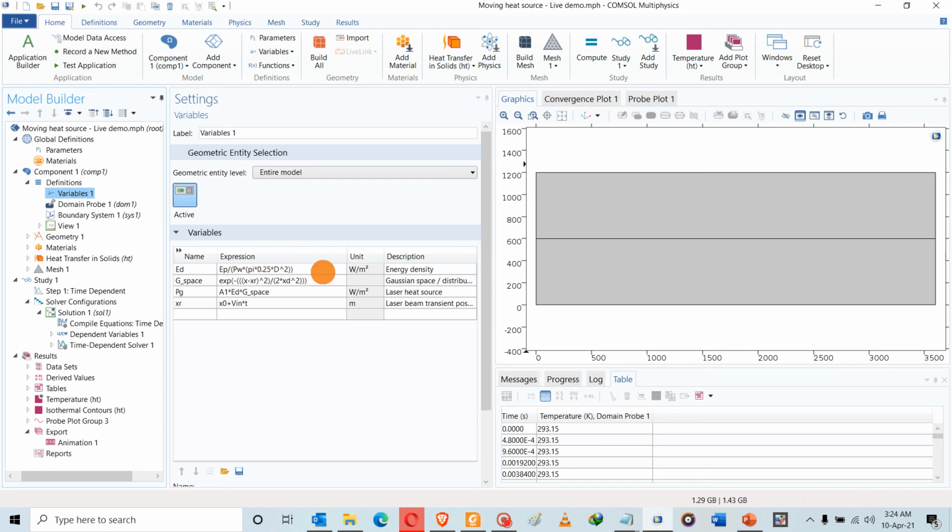I think in other lasers they use power if the laser beam is a continuous wave. So they use power there. You don't have to convert the pulse energy into power by dividing by pulse width. It's already power. And then you can just simply divide by the spot area. So then you have watt per meter square, which is the heat flux.